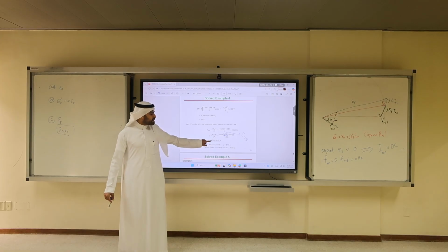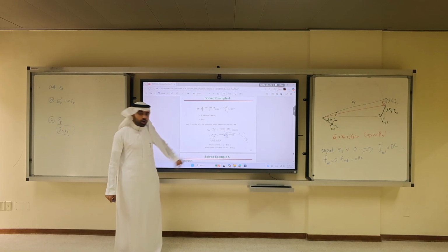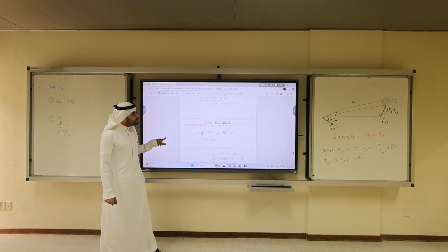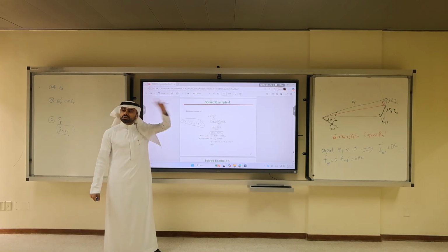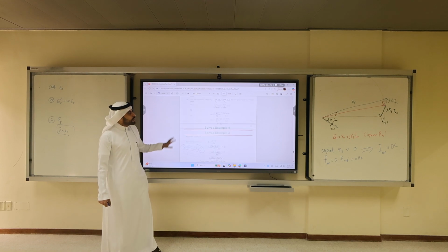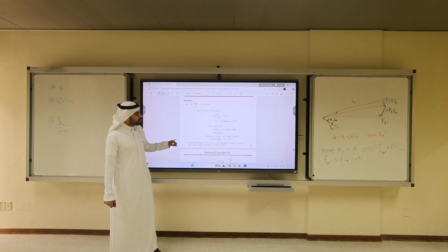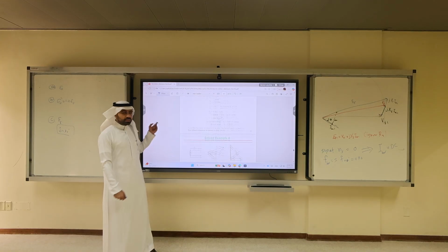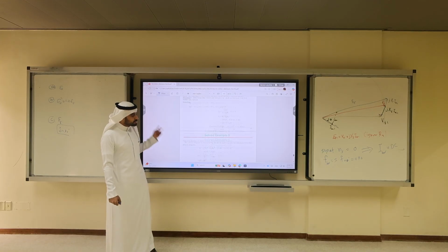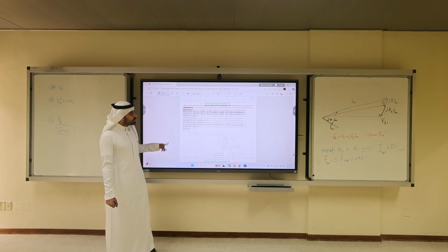What do we notice at the new IA? It's 29.9. In part B, it was 17.86. So that's almost twice part B or part A. So at maximum power, we draw so much current, almost twice the rated current. Is this good or bad? It's really bad.